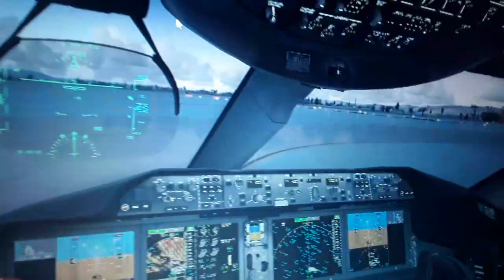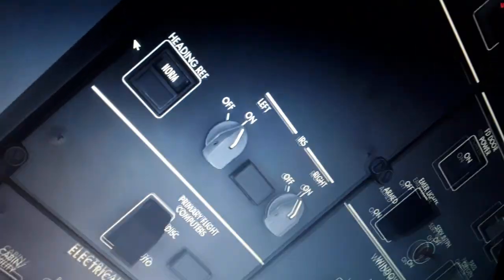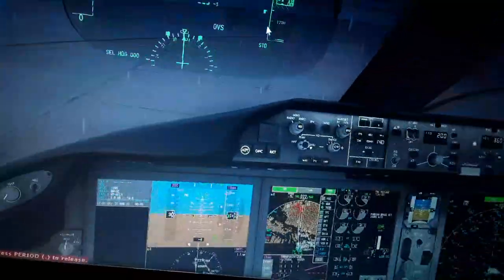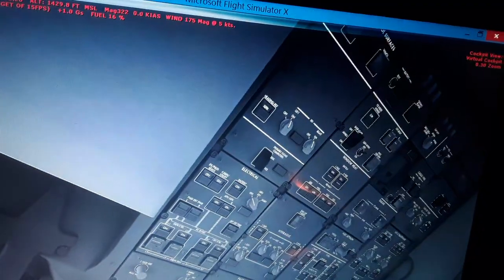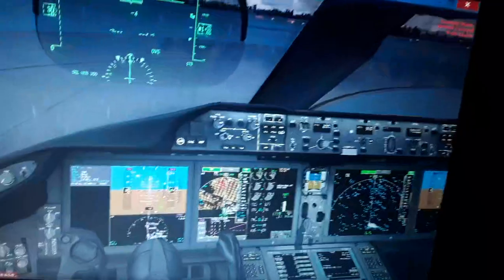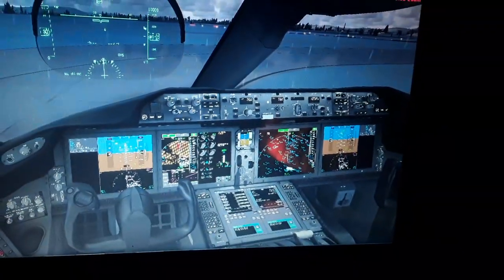You can see also over here in the overhead panel, we have the air data computer. You can see heading reference, IRS inertial reference system, primary flight control computer, flight control. We need the air data computer to display the pitot static and pitot dynamic for the airspeed, the pitot static for barometric altitude difference as we climb or descend, the laser gyroscopes, the GPS receivers, inertial acceleration and deceleration of the aircraft, the altitude in flight, magnetic north pole, true north pole, magnetic variation depending where you are in the world, the altitude of the aircraft above the ground, radio altitude. So all these indications, the angle of attack as it flies, the pitch attitude in flight, everything is affected by the air data computer for the pitot, static and GPS receivers. And we have a few more things to see, the flight controls here.